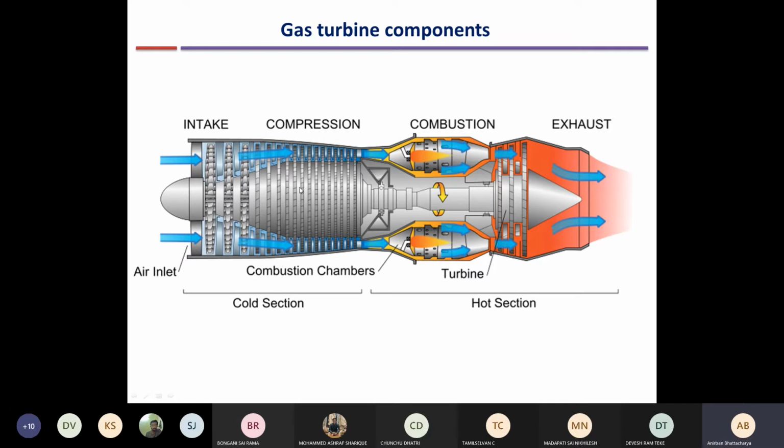And the second thing is that these compressors, which increase the pressure with the input of work, generally need a work input that is quite high compared to the work input required for the same pressure increase in pumps. So in steam turbine plants, the pressure increase occurs in the pump, right? We have multiple pumps which increase the pressure from say 10 kPa to 10 MPa. In a gas turbine, the pressure increase occurs in the compressor because the working fluid is in a gaseous state. As a result, the compressors require much higher work input as compared to pumps.